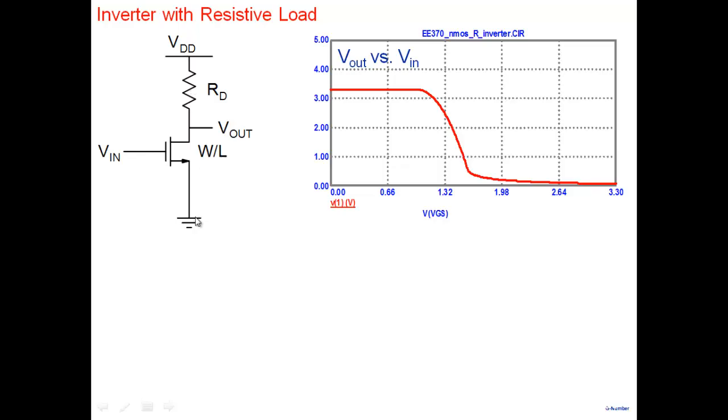The other terminal is ground. And we've already seen that if you take an inverter like this, when you don't apply any voltage, or the voltage is zero, the threshold voltage that we are taking for a transistor is about 0.7 volt or 1 volt, let's say. So the transistor is off. And so when you apply 0 volts, the transistor is off. This is connected to the supply voltage, which we'll take as 3.3, and so the output is 3.3 here. So when you apply a low here, the output is high, 3.3.